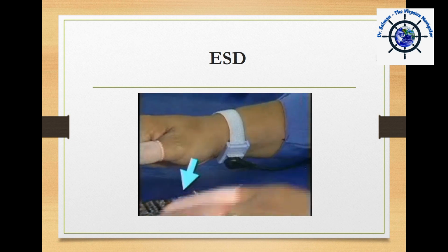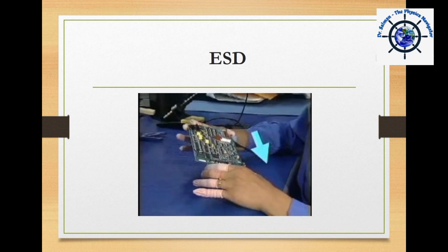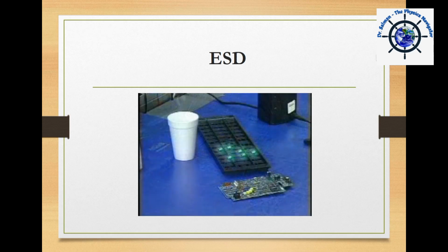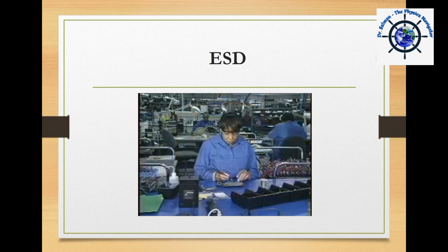The human body, most electronic components, and static dissipative materials are classed as partially conductive. They will allow grounding techniques to be used, but electrical charges are drained slowly. This is actually a desired feature in many cases, since draining charges slowly minimizes the chance of damaging electronic components.